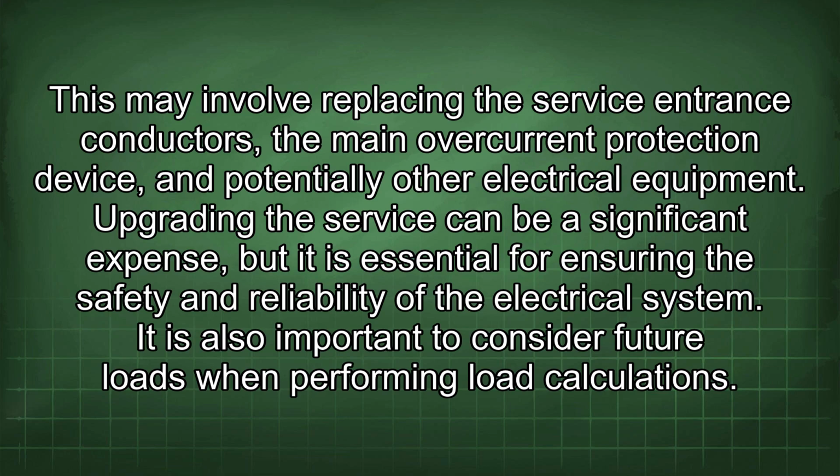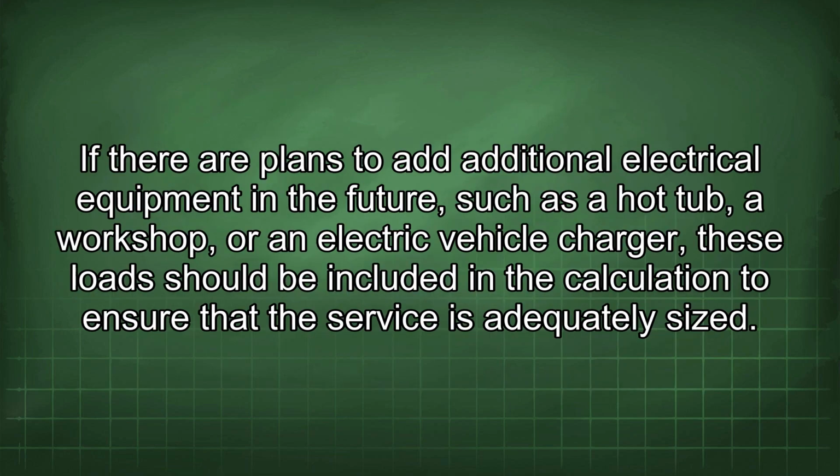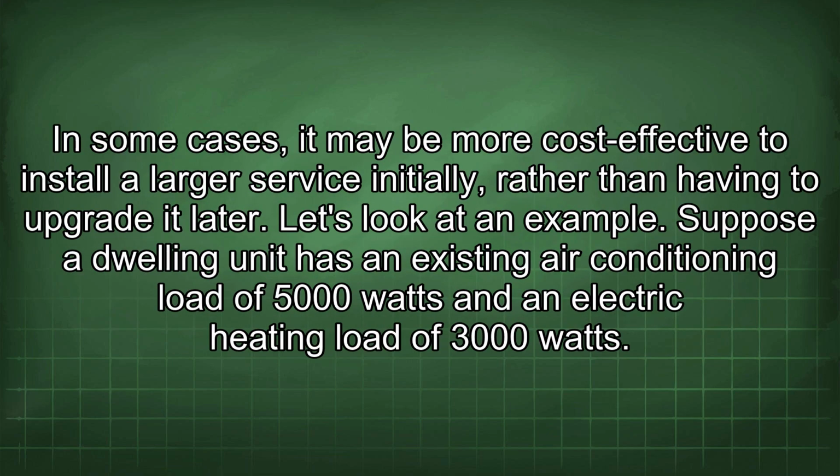Upgrading the service can be a significant expense, but it is essential for ensuring the safety and reliability of the electrical system. It is also important to consider future loads when performing load calculations. If there are plans to add additional electrical equipment in the future, such as a hot tub, a workshop, or an electric vehicle charger, these loads should be included in the calculation to ensure that the service is adequately sized. In some cases, it may be more cost-effective to install a larger service initially rather than having to upgrade it later. Let's look at an example.